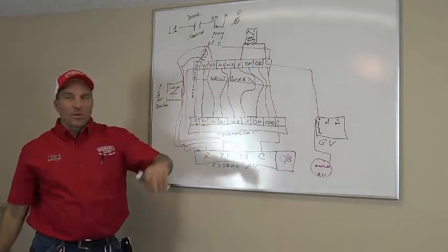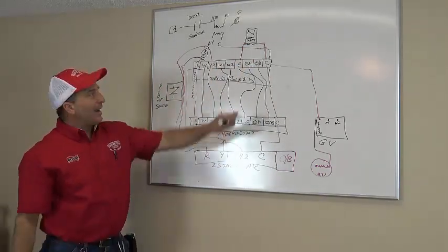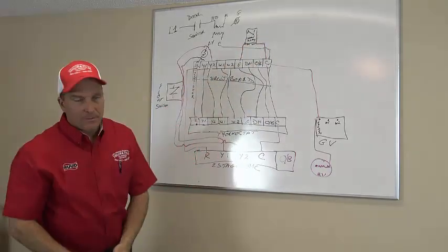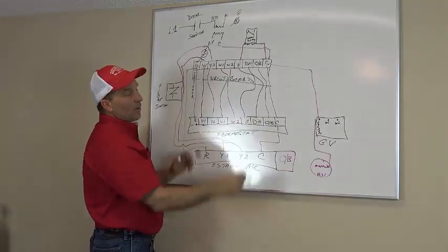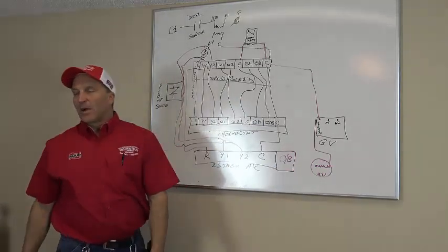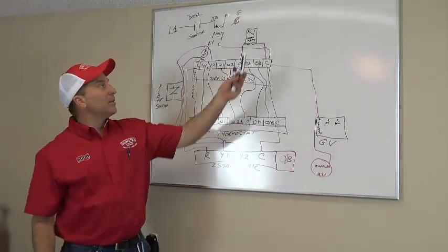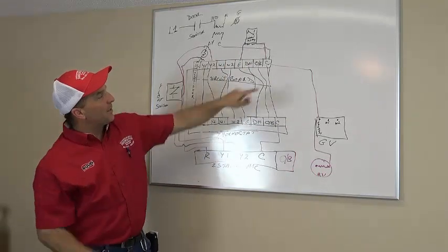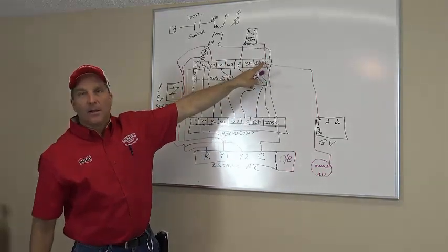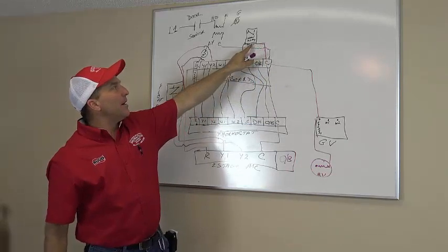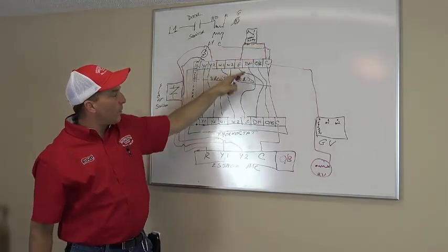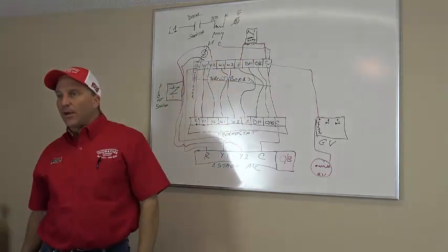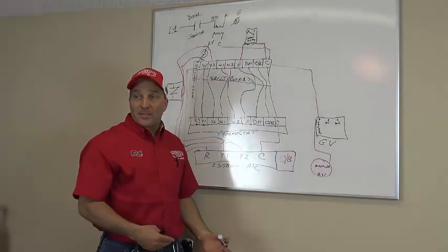So can you tell if you have a broken coil at your fan relay, like at your thermostat? Pull the cover off of your thermostat. I have a broken coil right now. What do I read? R and G. R to G, 0. 0. If my coil, because my common is broken up here, and my common's coming from here and following up and then coming here, and it's broken, so there is no passageway through all the way to my thermostat to my G, right? Right.